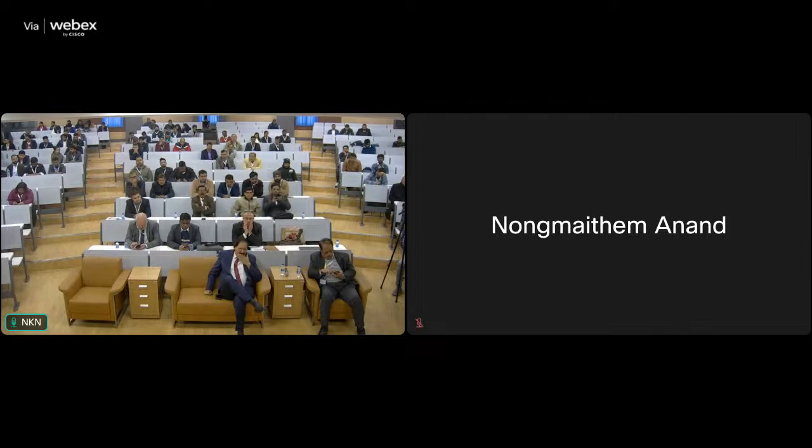Width we consider when we have to design the support of the roof, and height when we have to consider the design of the wall. Now, here the blue dot shows the 10-meter size, and I have considered ESR 1. So you will see that 9 centimeter thick SFRS, steel fiber reinforced shotcrete, is required.